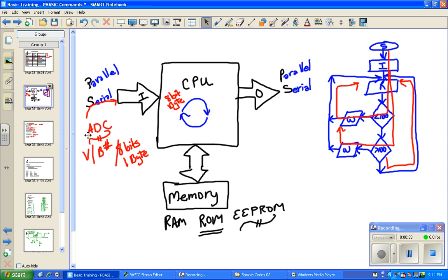Going back to our microcontroller, I'm basically running the same process control loop that I did in the past. This time I will be reading information from a single port, so it may look like I'm reading in serial information, but actually I'm reading in digital information, using the microcontroller to measure the time it takes for the value to change from one state to another state.